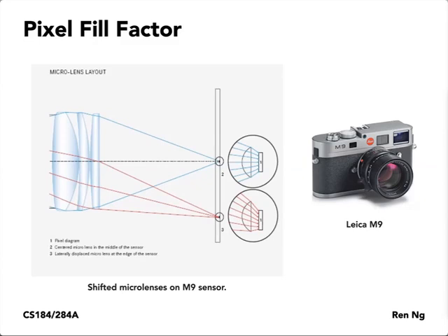And this is actually done in the sensor design of this chip. So the microlenses are not centered directly over the pixels, but they're actually at a slightly different geometric scale. They're slightly smaller in this case. Okay, so they're slightly compressed, but a very, very tiny amount. But that tiny amount of scaling has a very big micro-optical effect, okay? You might also note that this depends on the design of this lens, unfortunately, and exactly where it's going to be situated relative to the sensor. So there's a lot of different macro-optical as well as micro-optical engineering issues to be figured out at the same time.